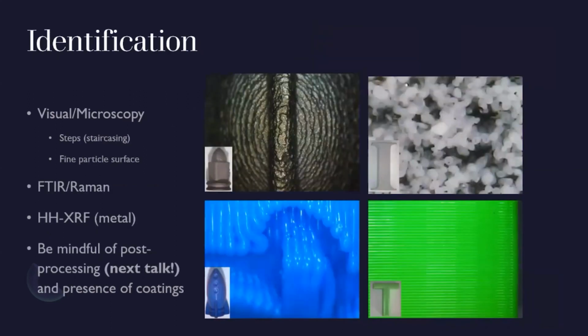I'd like to wrap up this presentation with one last topic, ways of looking at objects to determine whether they were 3D printed and perhaps with what method. A careful visual and microscopic examination is in order to find any obvious clues. Things to look for would be evidence of layering, as shown in the center of the slide. Be warned that sometimes these steps could be obliterated during post-processing. For SLS, the surface may appear to be composed of particle grains that are adhered together, as shown on the right, which happens to be an optical micrograph of the letter I in our 3D printed kit.